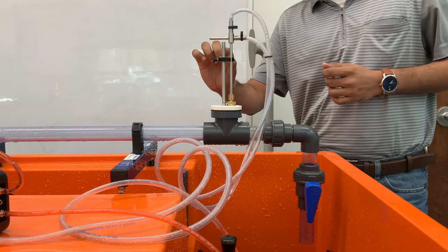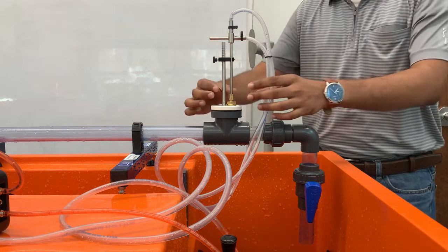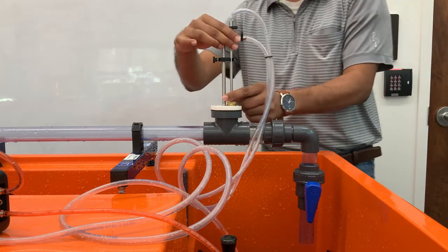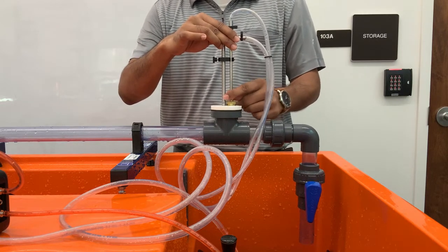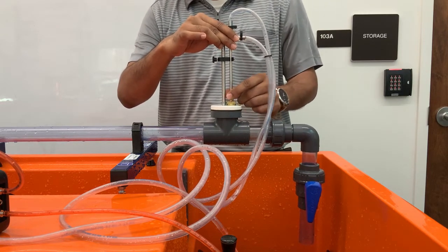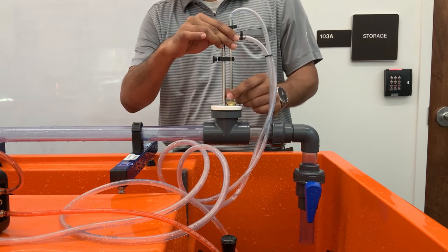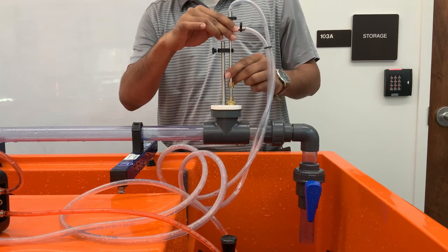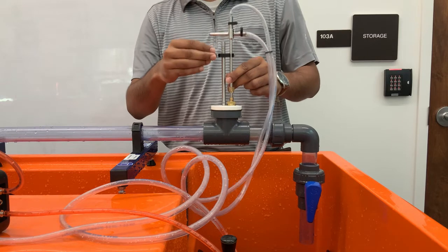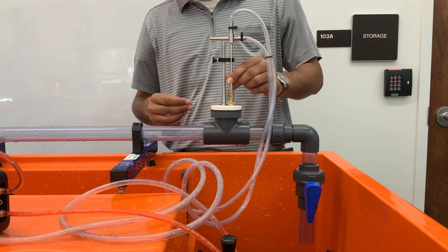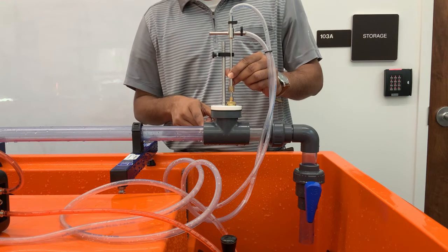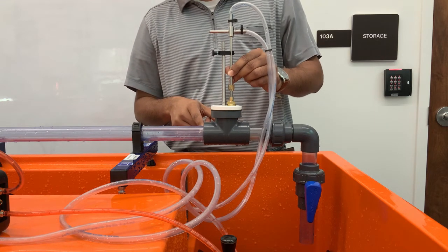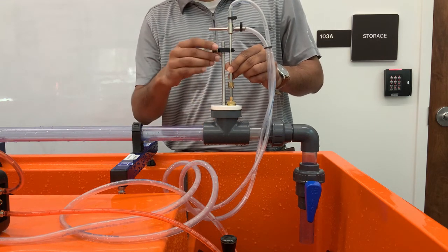You see there are notches here. I have to open from here to unscrew the Pitot tube from the system. It's open, and now this is also unlocked. So see, I can go up and down. That will change the position of the Pitot tube head inside the pipe. So I will start with the top.